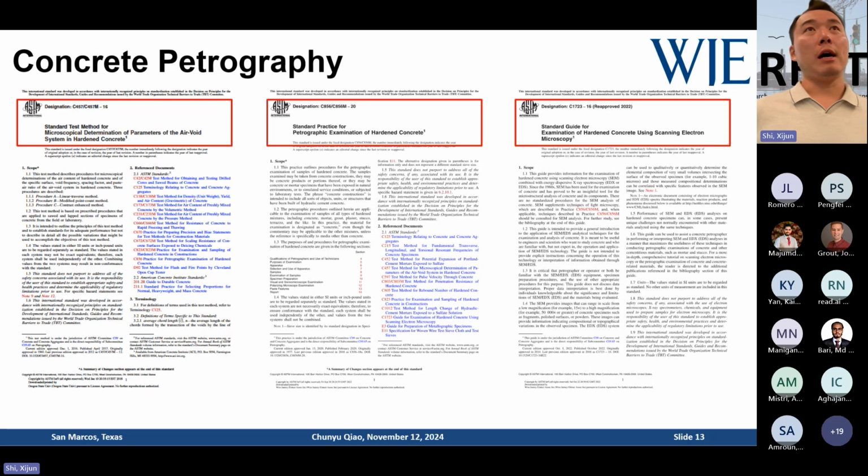And also, up in the north, not necessarily in Texas, but up in the mountain states, freeze-thaw damage or any de-icer damage are major concerns, especially for DOTs or other flatwork stakeholders or parking structures. So properly evaluating the hardened air void parameters is very important, because air entrainment is a major tool to fight against freeze-thaw damage.